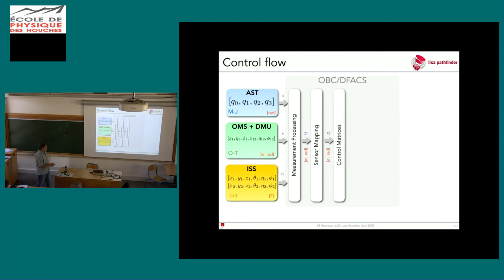Then you take a set of control matrices, a set of filter functions, if you like, which convert those into accelerations and torques per unit mass, per unit inertia. You decide where you're going to apply those onto which actuators and around which degrees of freedom, and then you send those off to different actuator algorithms.